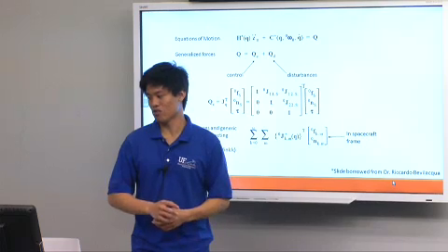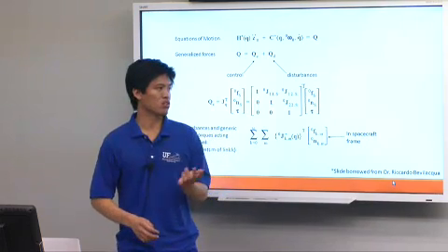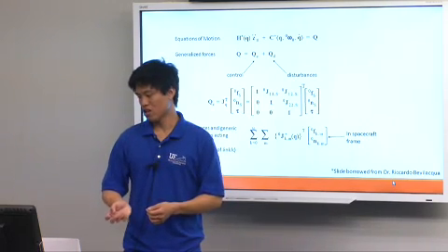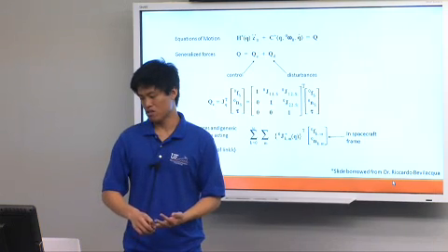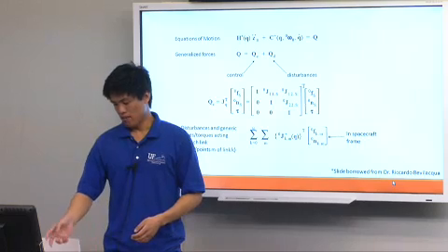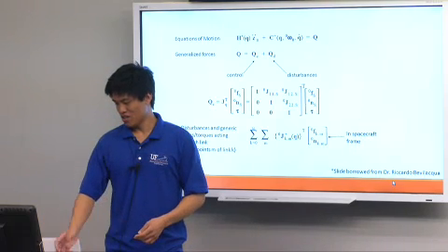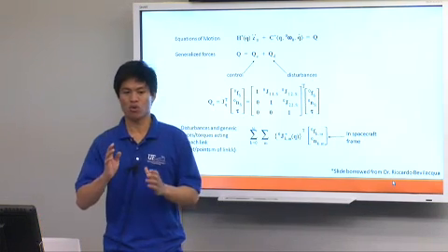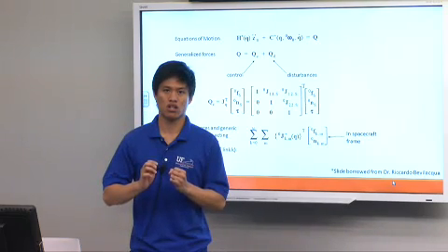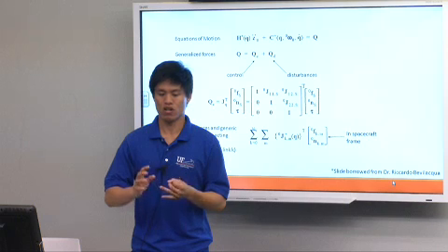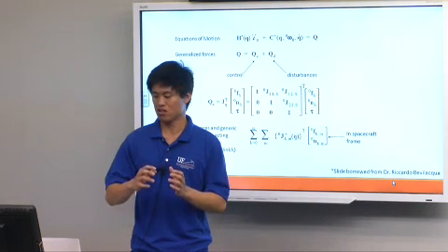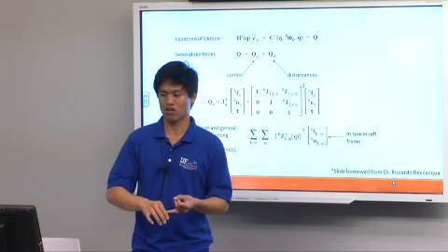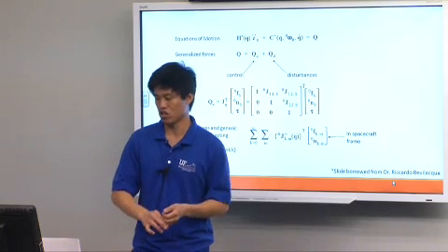I guess the vector, the way it's written, is equivalent to our generalized forces, and our generalized forces are pretty much composed of our control and disturbances. And our control, once you figure out, there's a Jacobian that maps, because again, we control the rotation rates, the attitude rates of the base and the center of mass, and we have to map that into something that we desire, which is our end effector and the location of the spacecraft base. And that's what the Jacobian is.